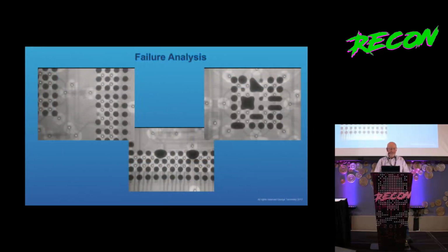And for failure analysis, which is really why the machine is around, this is the picture on the left. Top left has a missing ball. So this was placed, and there's one ball missing. I think everybody can see that up there. The others are shorts that happen. Remember, solder flows. And if you put enough flux in there, it'll short out, and that's what happened there. And the top one is actually a pretty bad one, where because of surface tension, it'll adhere to the next one. So there you have it, just like if you're soldering a pipe.